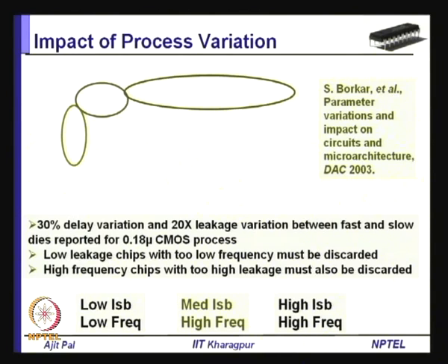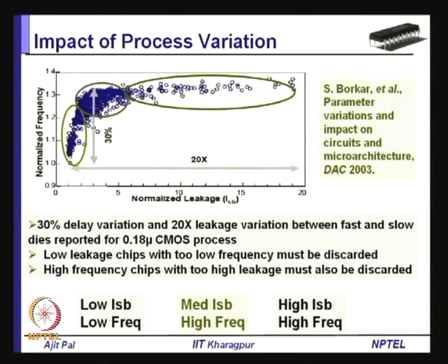And as we know, this channel length variation also leads to variation in the threshold voltage, because of VTH roll off. You may recall that in deep submicron technology, as the channel length varies, it leads to variation of the threshold voltage. That means, if the channel length becomes shorter and shorter, the threshold voltage becomes smaller and smaller. Okay. And here is the impact of process variation.